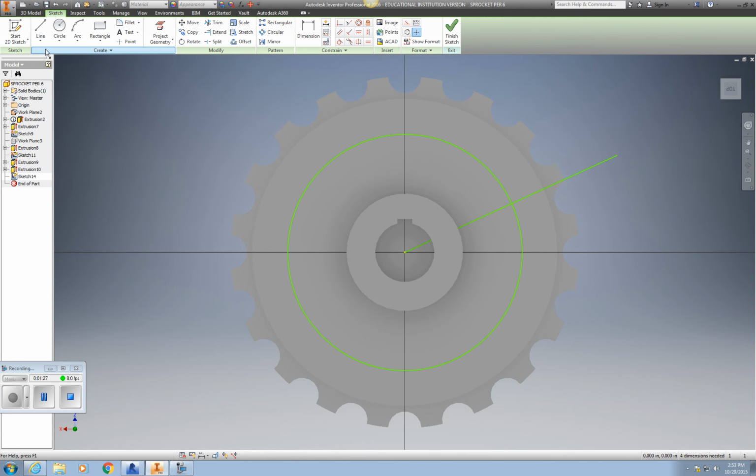To double check that, let's draw a line from the actual center horizontally, hit escape, and do a dimension check, checking the horizontal and the angular line to see what the angle is. In this case, it did not go to the proper angle, so I'm just going to drop the following angle, which happens to be 24.44, but I'm going to edit that and make it 30, and then hit the checkbox. Now we know it's at 30 degrees.